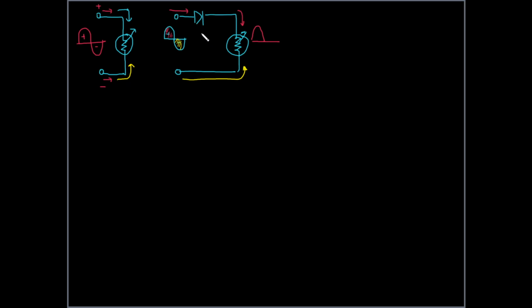And if it's very high, it's almost equivalent to an open circuit already, and there will be no continuity here. The current coming from this terminal is going to be very small because of this very high resistance, because it's reverse biased. So very small current, very small deflection, approximately 0 deflection.